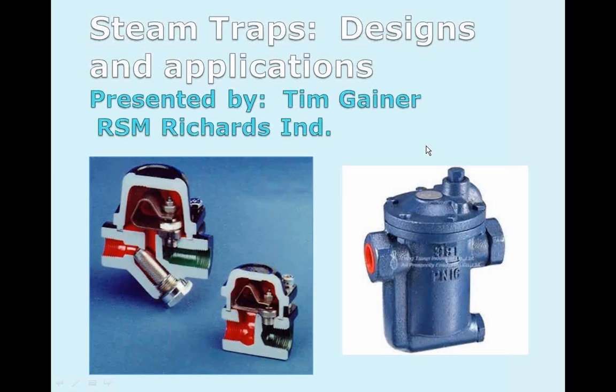Sounds like it's dependent on each bucket trap, and you have to look it up depending on the bucket trap. And there's stainless ones out there. Most of the buckets are an iron of some type, typically cast. But I've seen stainless buckets in smaller sizes, so those will have much higher pressure ratings than a larger one would. Right.